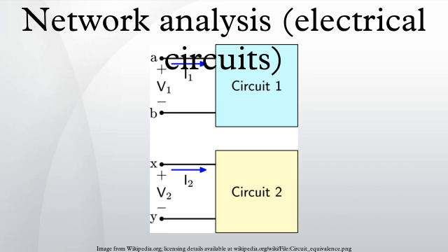A resistive circuit is a circuit containing only resistors, ideal current sources, and ideal voltage sources. If the sources are constant sources, the result is a DC circuit. Analysis of a circuit consists of solving for the voltages and currents present in the circuit. The solution principles outlined here also apply to phasor analysis of AC circuits.